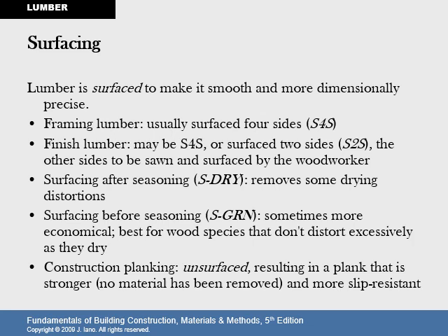Surfacing after seasoning is the S-dry. It removes some drying distortions. Surfacing before seasoning is the S-green, GRN. Sometimes more economical, it's best for a wood species that doesn't distort excessively as it dries. Construction planking is unsurfaced, resulting in a plank that is stronger, since no material has been removed, and more slip resistant.